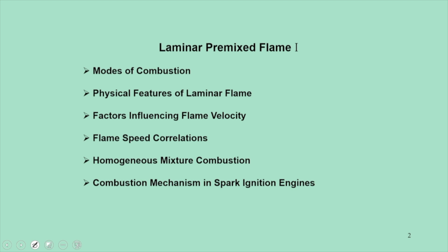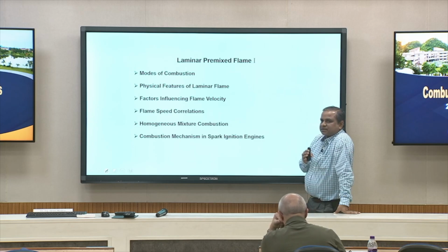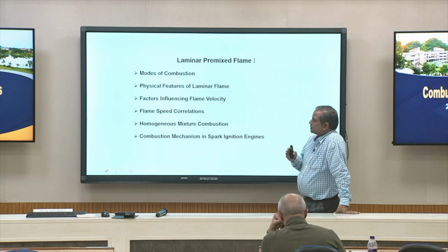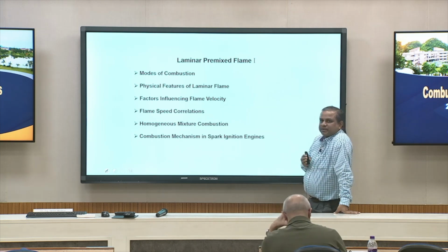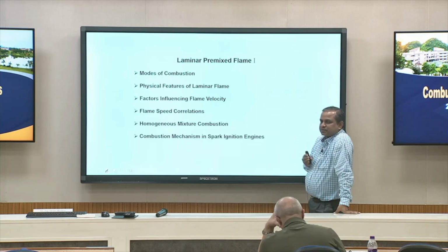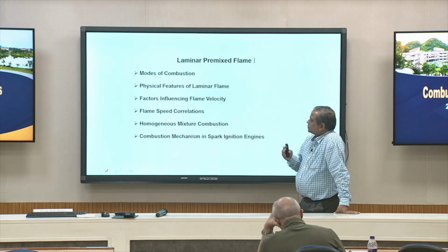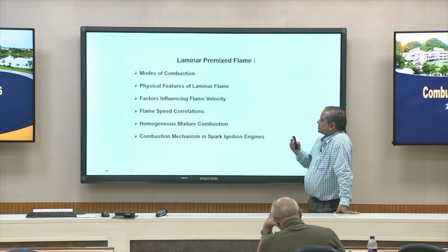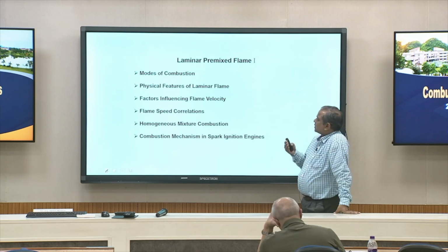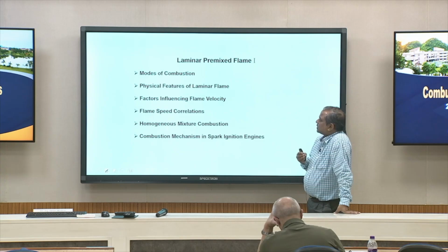Flame is nothing but a surface that essentially distinguishes the region between the charge and the combustion products. In the combustion medium, the flame propagates or moves. When it moves, because of the increase in pressure and temperature during combustion, it also subsequently moves to ignite the fresh charge.